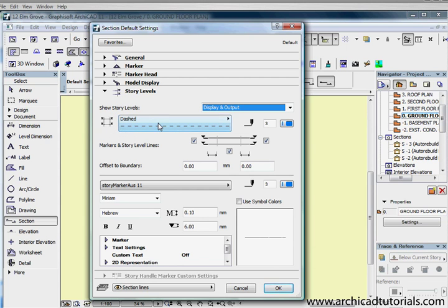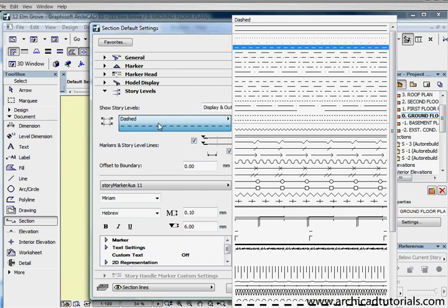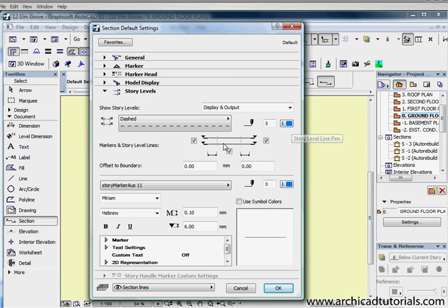So this story, once again, we can choose the different line types, showing as dashed at the moment. We can designate the pen type, we can put heads or markers on both sides, turn the middle bit off. Over here I can also designate the distance between the edge of the last element measured and where the markers start, by changing that dimension there.